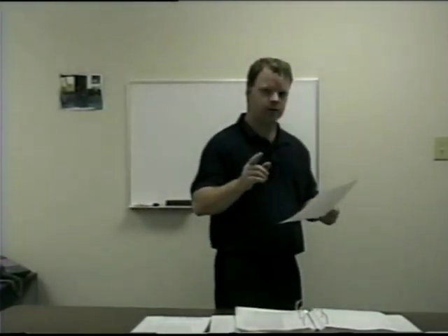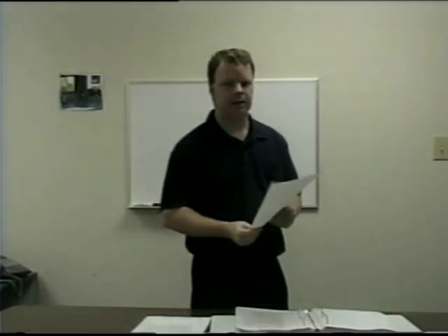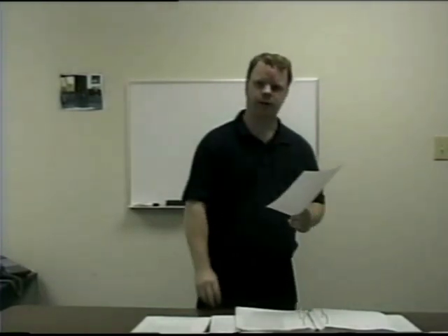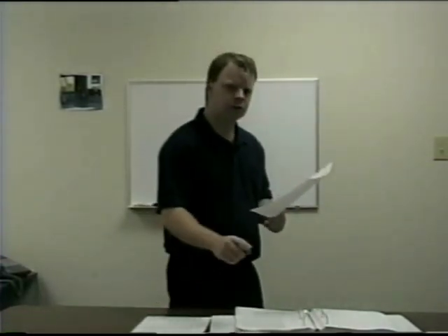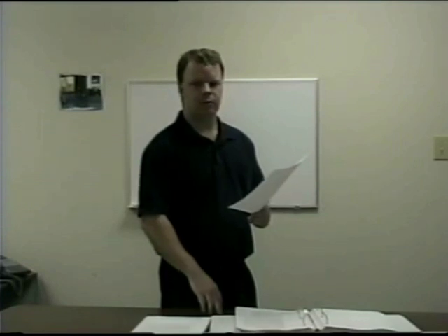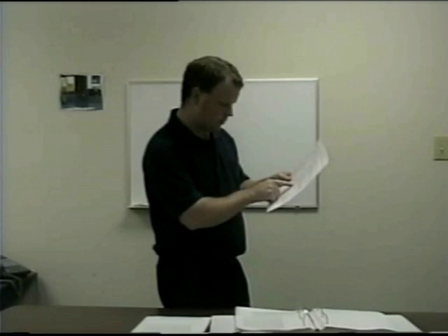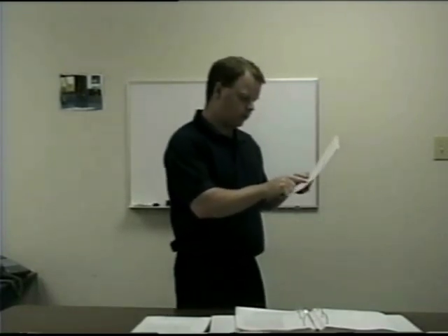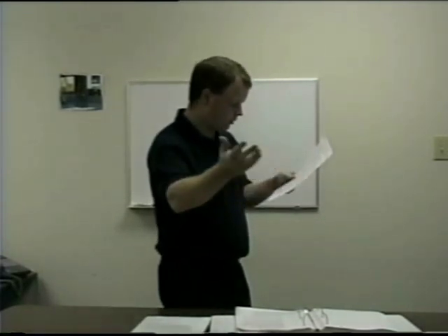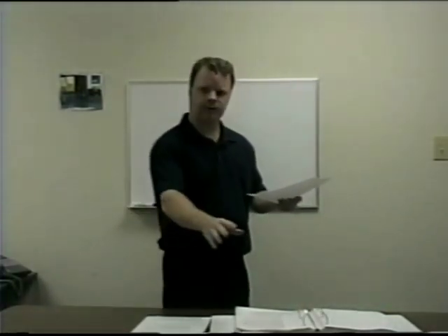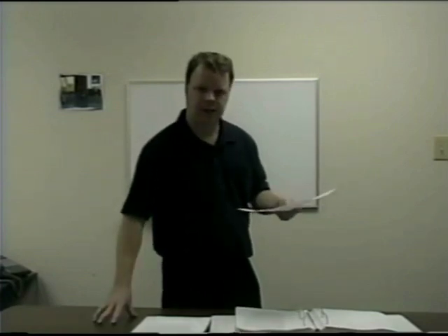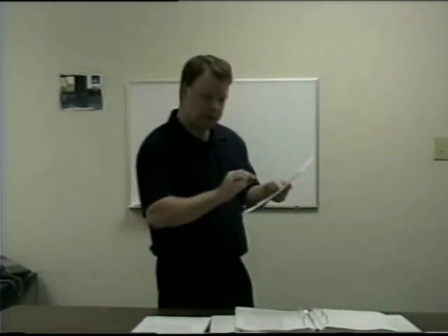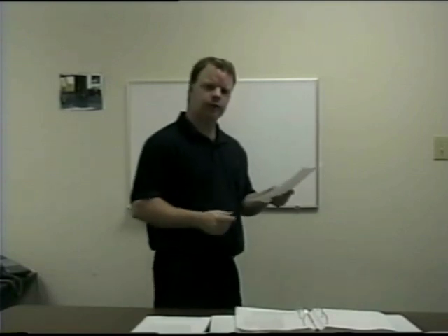Watch these guys. Don't think that they're going to abide by something just because you say. Enforce it. Make sure they remove that from your site. And when they come back with more material, make sure that they don't come back with the same stuff they removed, because I've had it happen on my jobs. Okay, verify felts for use with asphalt. Are asphalt saturated? Felts for use with coal tar saturated. Make sure they're using the right pound felts. I've had roofers try to use 15-pound felts where the specifications called for 30-pound felts. We want to inspect, make sure that the owner's getting what he's paid for.